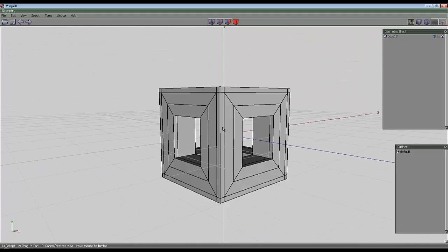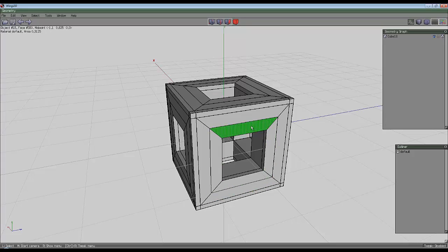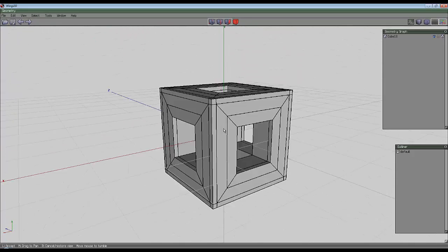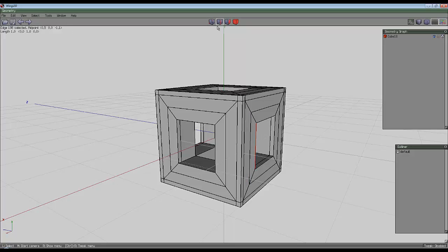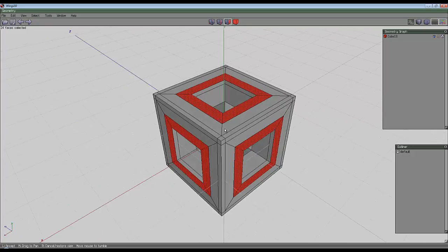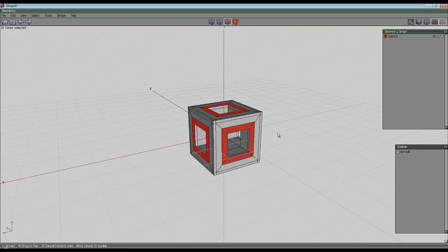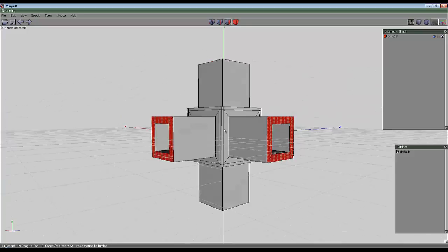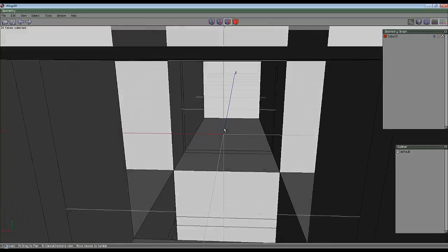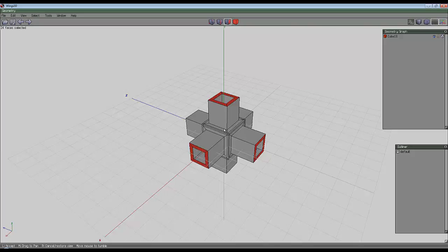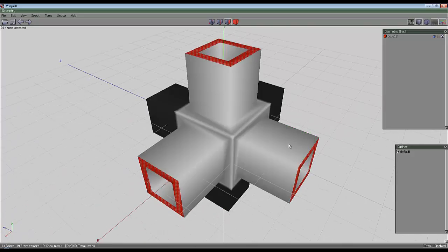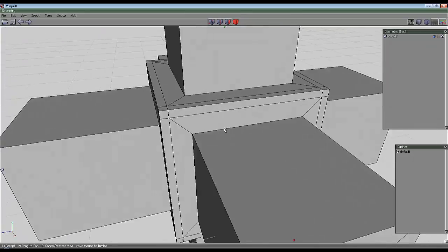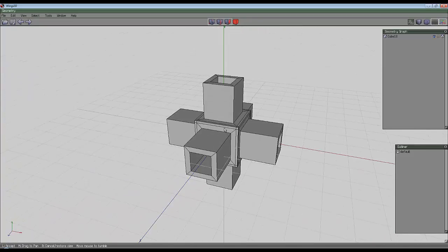So that's quite handy. The next question is what can we do here? We can extrude this shape. So let's see. This is sort of building it all in one go. So if I use I for identical, having selected those, if I go extrude normal, it's sort of creating my shape all in one go without having to do any welding or anything. We've still got some good geometry and bad geometry mixed in here if you have a look, but we can sort that out as we go along, I think.